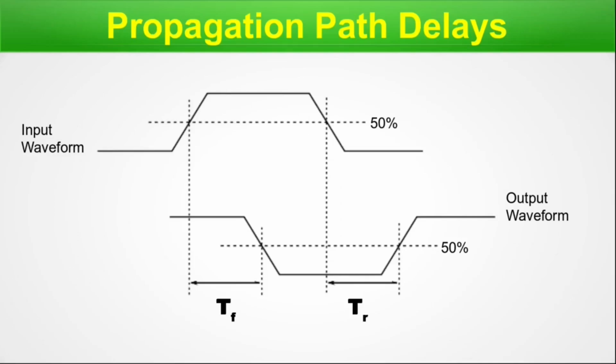We can see in both the cases that there is a horizontal dotted line. See, this is the horizontal dotted line which cuts the waveform at 50% height. So if I consider this is the height from here to here, it cuts at the 50%. In both cases, it is the same. The y-axis, that means in this direction, is the voltage, and the x-axis, the horizontal direction, is time. So we have voltage in this direction and time in this direction.